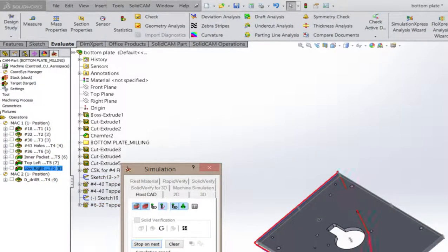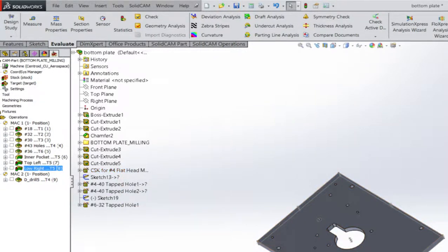Notice that they're the same tool number, tool 5. If I don't do anything and put a separation in between tool 5 and tool 5, it's going to cut these two sides, and it's going to go immediately to these other two sides and start cutting that. What's bad about that? There are clamps in the way. So what we'd like is, after this tool path is done, for the machine to stop and give us time to move the clamps.